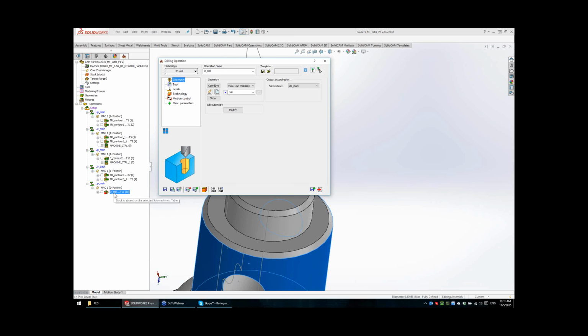Stock is absent on the selected submachine table. The message is clear. I didn't select the correct submachine. My part is on back spindle and I select to work on upper turret main spindle. Change it to upper turret back spindle and that's all. Save and calculate. Very simple.